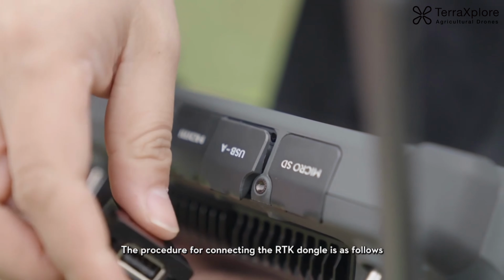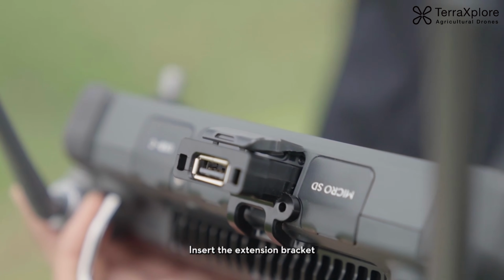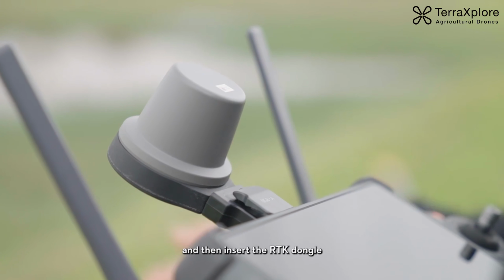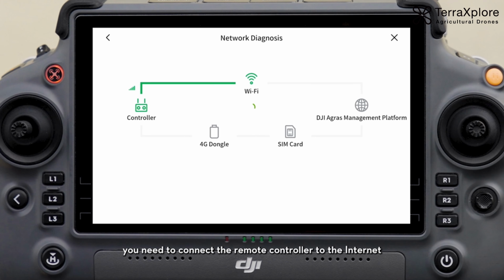The procedure for connecting the RTK dongle is as follows. Insert the extension bracket, tighten the fixing bolts, and then insert the RTK dongle. To plan a field on the remote controller by using a custom network RTK, you need to connect the remote controller to the internet, but the Agras drone does not need to be powered on.